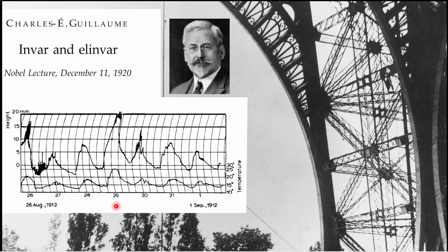And here you see this very nice diagram from his original Nobel lecture, which shows the sequence of height of the Eiffel Tower as a function of day and night, so as a function of temperature, obviously, that he was able to measure with his new Invar alloy, the classical one being an iron 36% nickel alloy, in reference to the thermal expansion and shrinking of the entire Eiffel Tower.